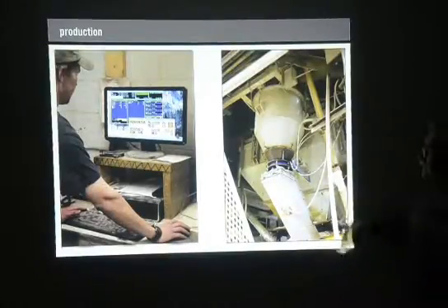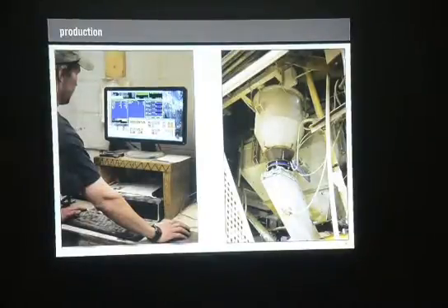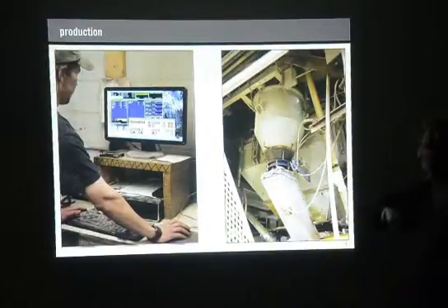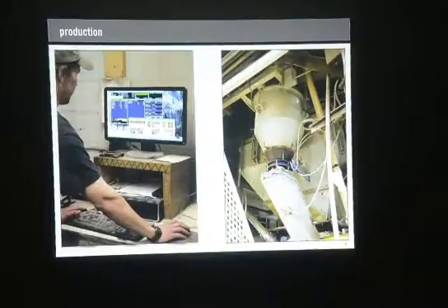What's in back of here is a hopper, and the hopper mixes color. There's a small little cylinder, smaller than this one, that has color that's added to it. The colors are dry pigments, and then a minimal amount of water. Not a lot of water. Why? Because it's called zero slump at that point, because it doesn't slump. But I will say this, that when the block comes out in that last slide, out of the production line, it's like Jell-O. We could take our fingers in our hands and actually move it because it hasn't had time to cure. So these things do take time to cure. They don't come out automatically ready to go, for sure.